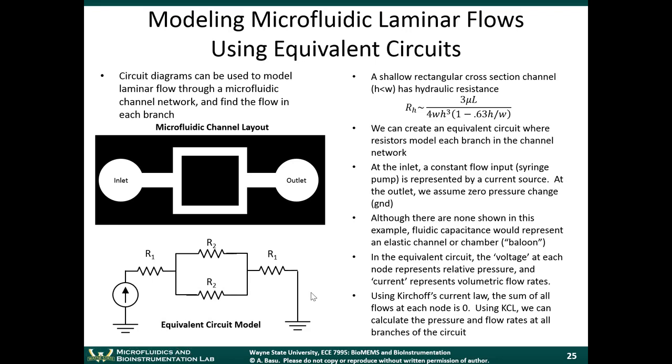So this slide is about modeling microfluidic laminar flows using equivalent circuits. Most of us have done some sort of circuit diagram analysis. In a typical circuit diagram, we draw some resistors, we draw some capacitors, and then we solve for the voltages and the currents at various nodes of the circuit. We can use things like Kirchhoff's current law and Kirchhoff's voltage law to do that. If you haven't done that, I can help you do those types of analyses. They're quite intuitive to do.